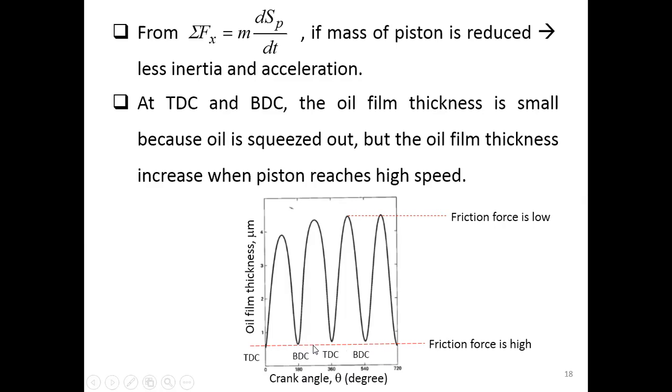Why? Because when the piston moves down to the bottom dead center, or moves up to the top dead center, the oil is squeezed out. When we say oil in this lecture, it always means the lubrication oil, not the fuel. The oil here is squeezed out when the piston is at bottom dead center or top dead center. That is one reason.